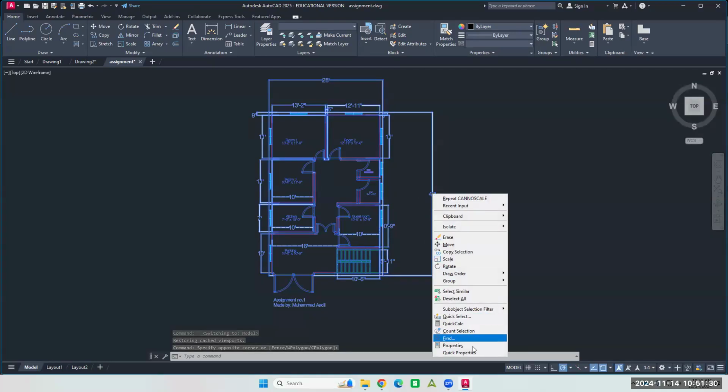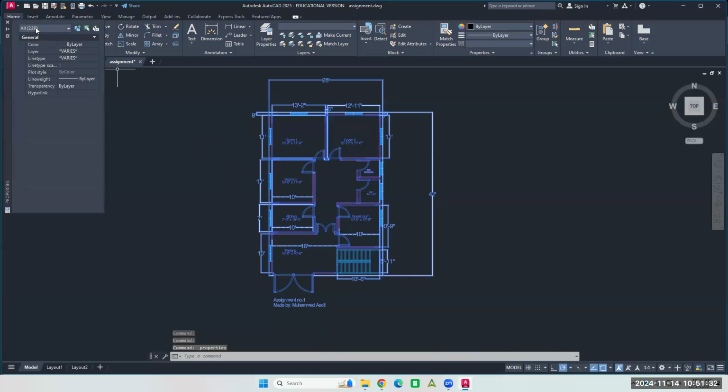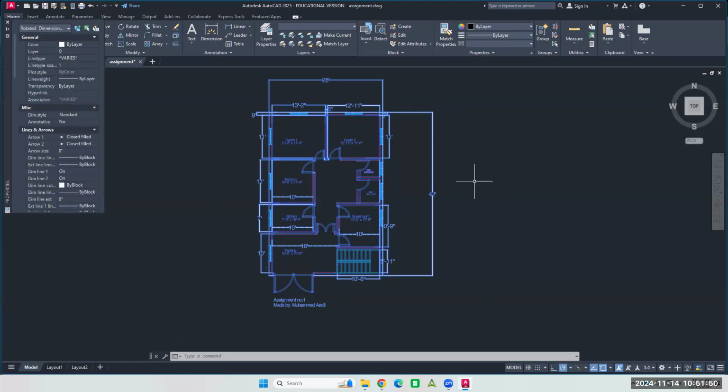And right click and go to properties. And then you can sort, because it says all, and I can sort by, they call them rotated dimensions, right? But that's just your dimensions. There's 19 of them. You can see the number, right? And that looks about right. There's 19. So I'm now gonna look at just dimensions. So even though everything got selected, I'm just choosing dimensions.